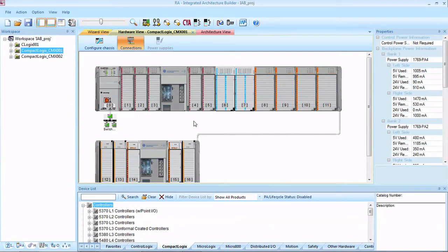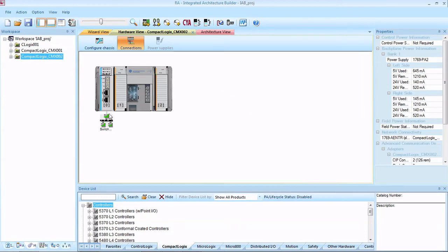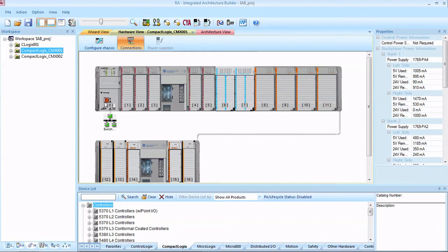You see that it filled out 2 banks of I/O and then an extra one to be able to fulfill our I/O requirements. But what it didn't do is it didn't break any rules or put a module in the wrong place, or we didn't undersize a power supply. It did everything for us. And so now again we have a bill of material that you can send.